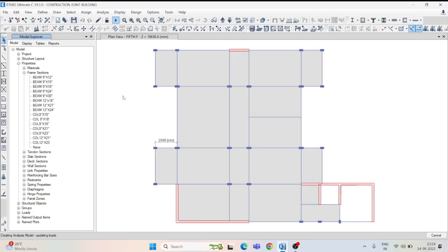Before, we have seen how we check the deflection in creep coefficients. In creep coefficients you have to multiply by 3, but in creep analysis there is no need to multiply by 3. Whatever deflection value you get, just subtract the axial shortening UZ value, and then compare with span by 350 or 20 mm. Whichever value is less, compare for both, to see whether it is under the limit or not. Accordingly we have to decide.